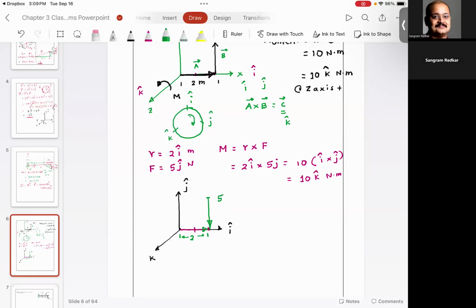Now you agree with me that the vectorial representation that I have drawn shows that these arrows coincide at the same point. However, I want you to think about it. If I were to just calculate the moment, radius times the force is 5 times 10, and can you see that the moment will be negative because my thumb would be going inside the board. Do you agree with me?